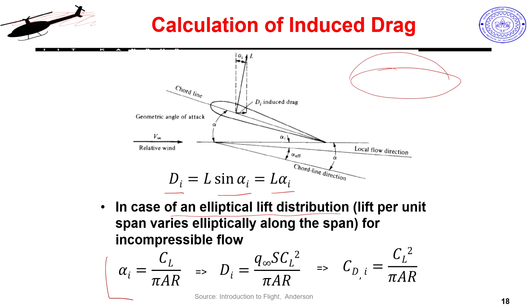Like I said, if you want to look at the derivation, you can refer to any good book on aerodynamics. They will all explain this. So, we get this expression for the induced angle of attack. It is now a function of my lift, and of course, pi is your normal 3.1415926 or any approximation of that, and then this new term, which we have already looked at, is the aspect ratio. Normally we use this symbol for aspect ratio. So, it comes out to be like this.